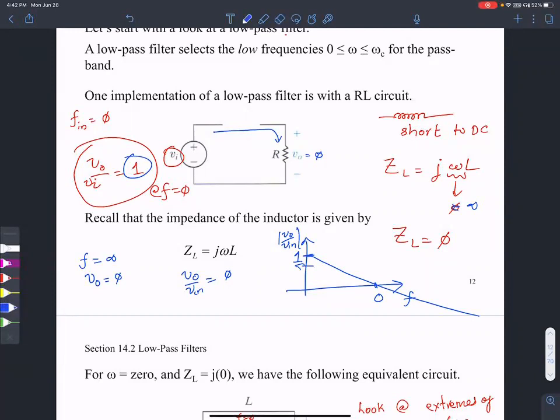That's a low pass filter, right? A low pass filter should pass all the low frequencies and it should stop the high frequencies. But this guy is a very crude approximation, a very crude model that is passing low frequencies and stopping high frequencies. So you look at the gain, high frequencies have a very low gain. Does that make sense?